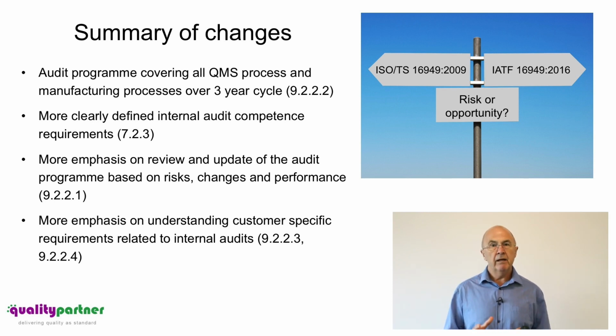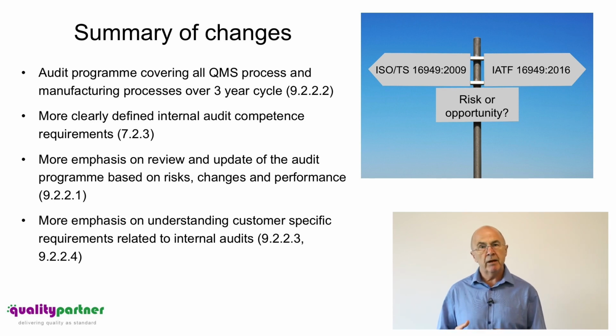And finally, there's far more emphasis on customer-specific requirements, making sure that when we're doing our internal audits, we're incorporating the customer-specific requirements into our internal audit process. We're not doing a 100% compliance check, but we're sampling customer-specific requirements to make sure that the process to identify and implement them is working effectively.